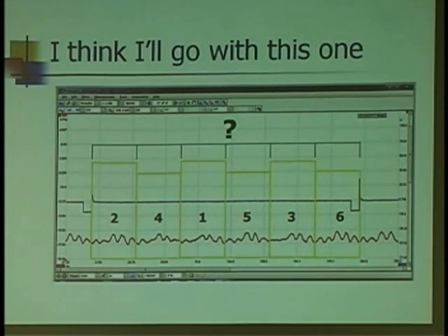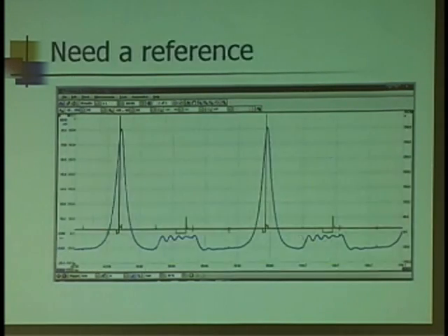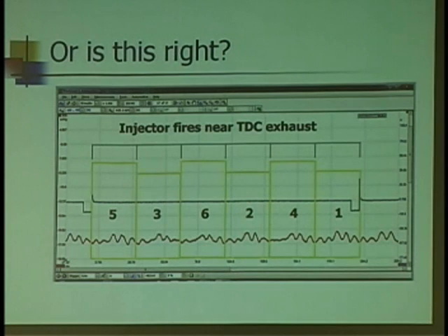What if I triggered on number 2 ignition? Then I'd have to use that one, wouldn't I? Because I would be starting off TDC on the exhaust, then BDC, and this is not going to be accurate because it's split up more than in 4s. But I'm going to be 360 out of phase if I use the ignition event as the trigger. Do you see where I'm going with that? You see what you have to think about depending on what your reference point is. Okay?